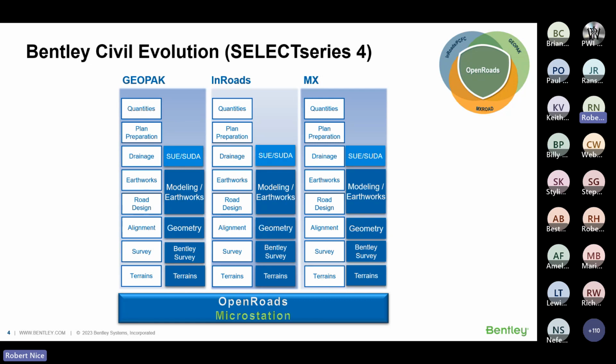And this is where we started to see these new menus appear, these civil elements, these geometry tools. You can still use the ALG, the ITL files and DTMs and all that, and your regression, cant and turnout tools were all exactly as before, but these geometry tools appeared under these task menus.